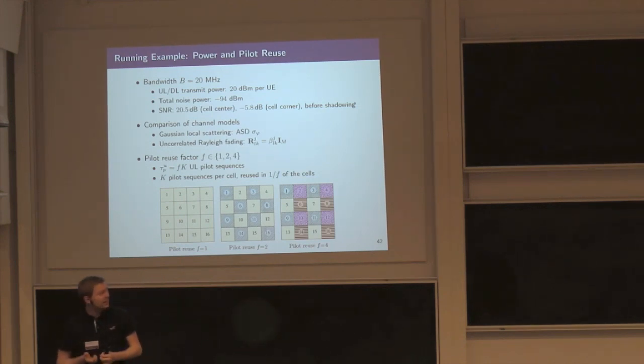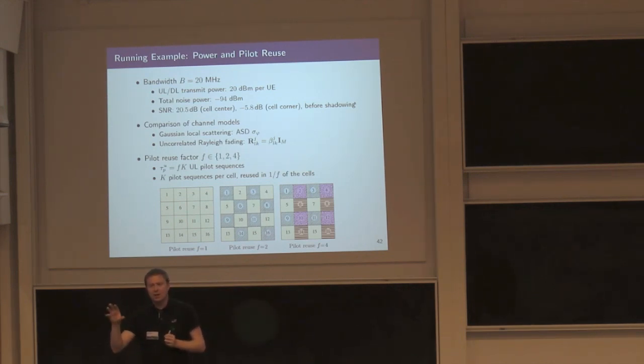But you will need to spend twice or 4 times the number of samples per coherence block to estimate the channels. And that reduces the number of samples you have available for data transmission. So you reduce the factor in front of the log, but you increase the SINR on the inside of the log. And there is some kind of balance when one of these effects is dominating.